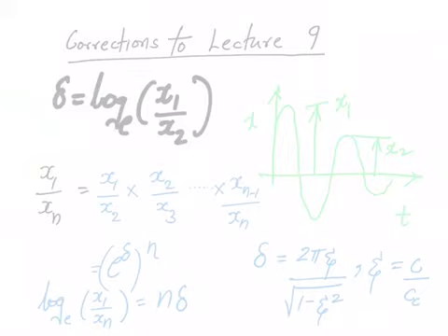In the last lecture, we talked about logarithmic decrement, which is defined as the natural logarithm of x1 divided by x2, where this is the plot you can see here. X1 is this displacement and x2 is this displacement. I already talked about how this corresponds to an underdamped case, and the amplitude decreases exponentially, but there is a periodicity associated with this particular curve, and all those things we talked about.